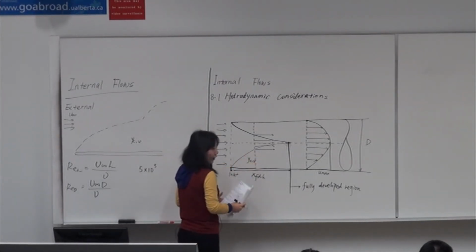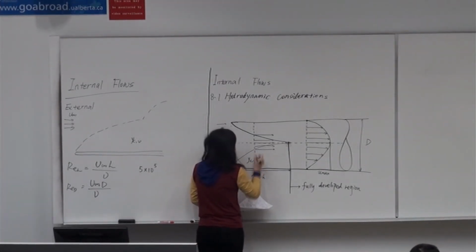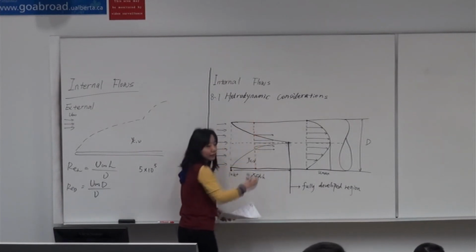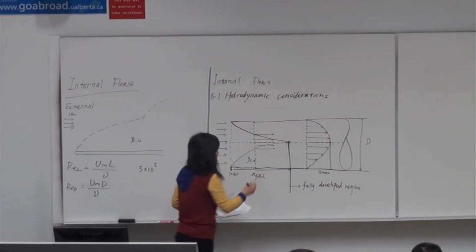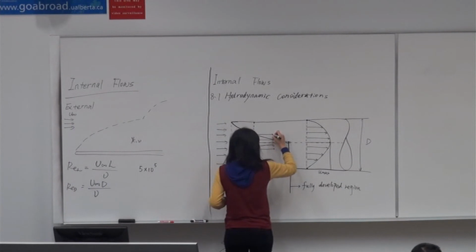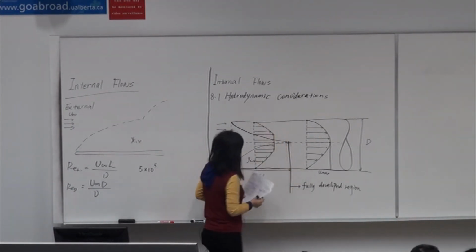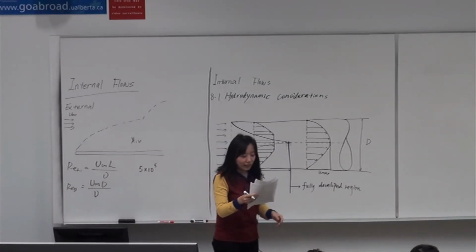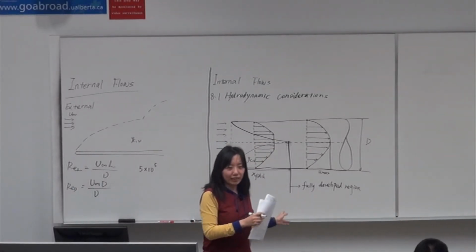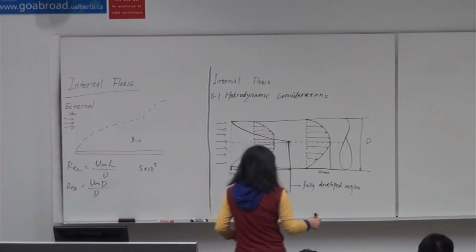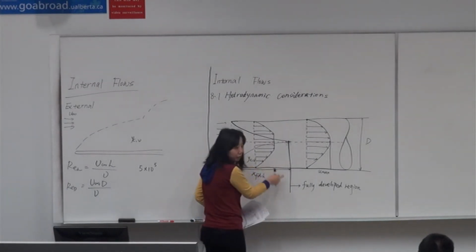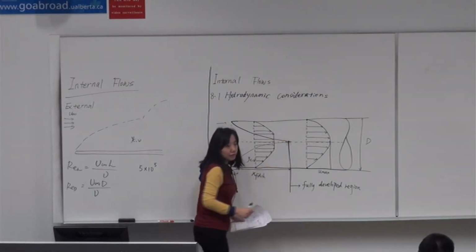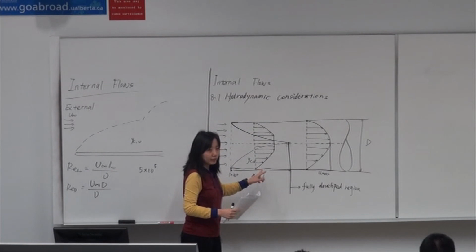Inside the boundary layer, it is zero at the tube internal surface and almost obeys a linear change. It looks somewhat like a trapezoid shape, not parabolic, before the point where the two viscous boundary layers collide.